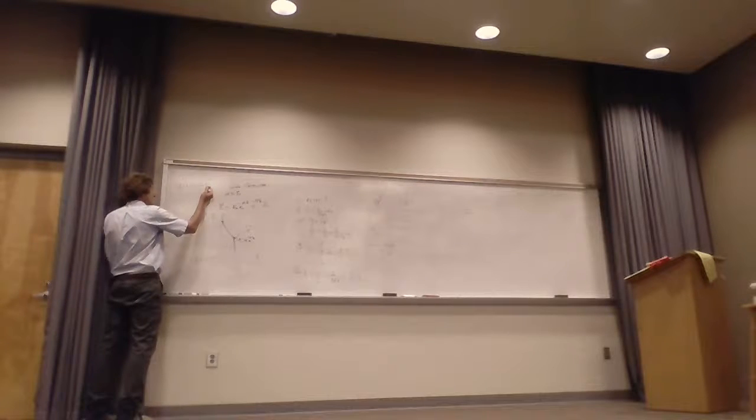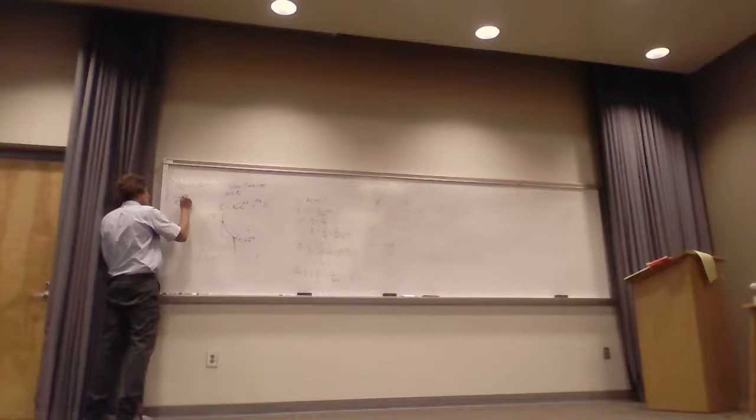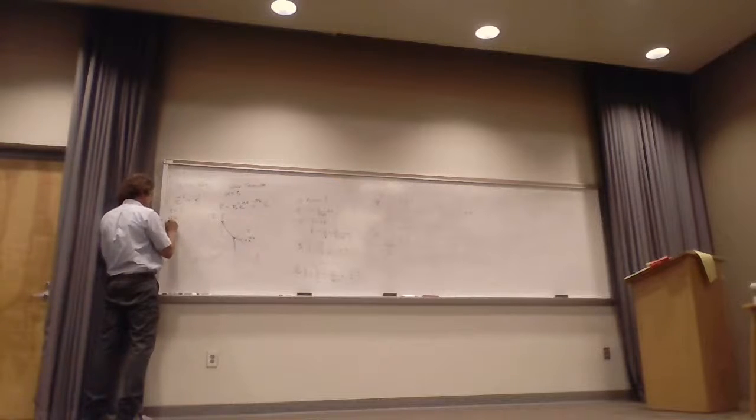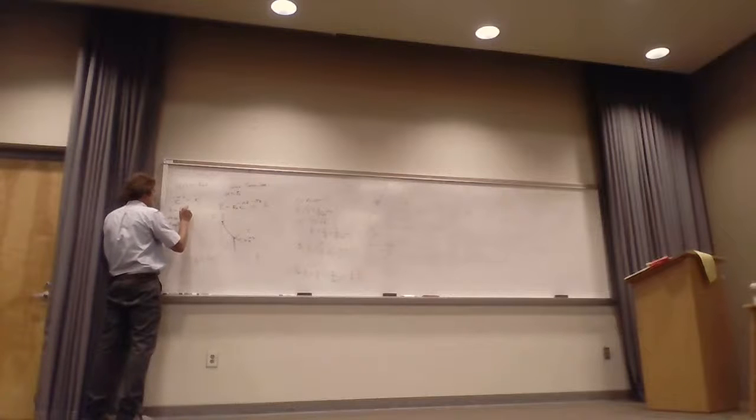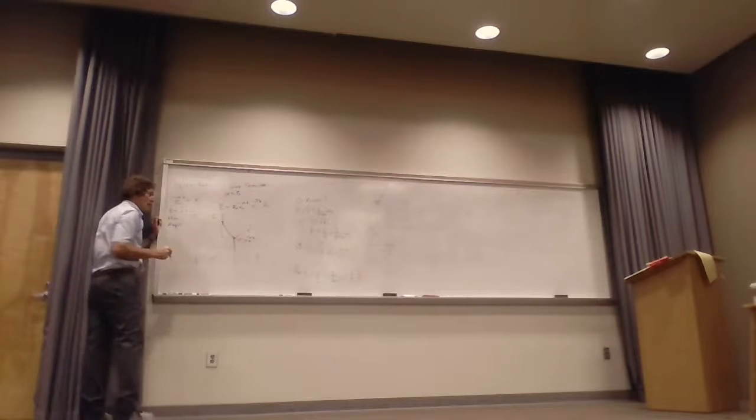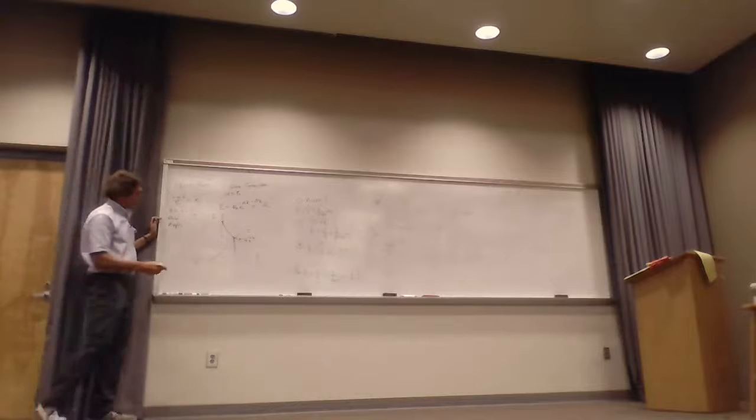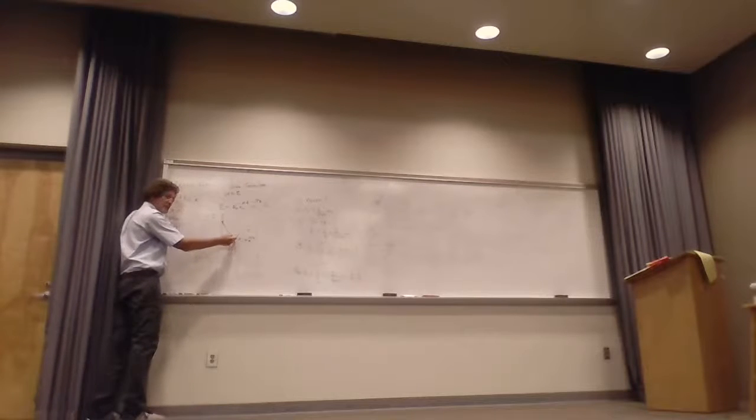So if I take this quantity and make it equal to e to the minus 1, basically z is then given the distinction of being called the skin depth. And it's simply 1 over alpha. And that's the value when the E field will go down to e to the minus 1, or about 37%, of its peak value.